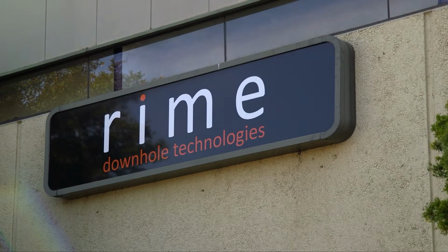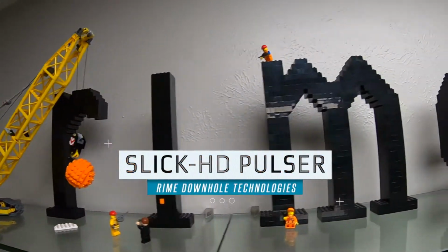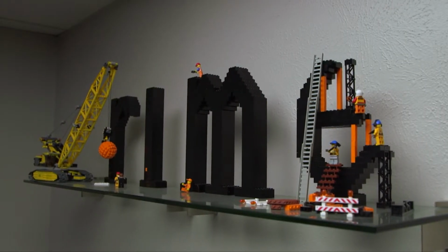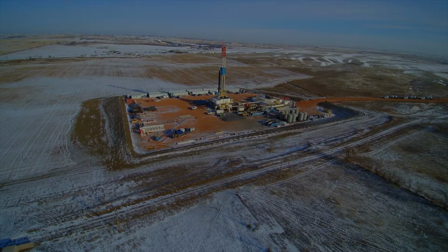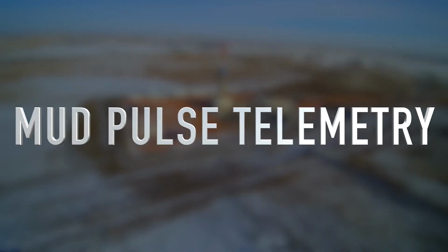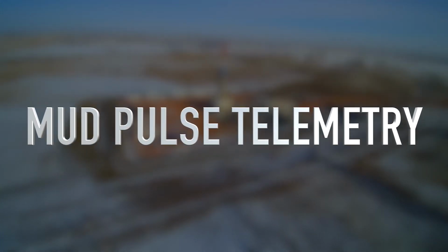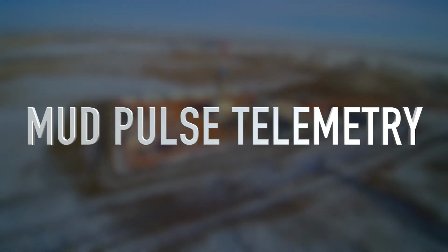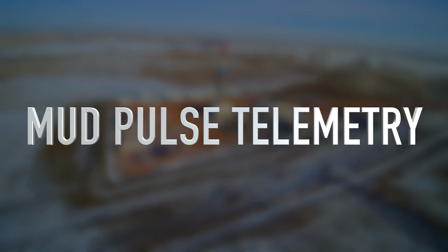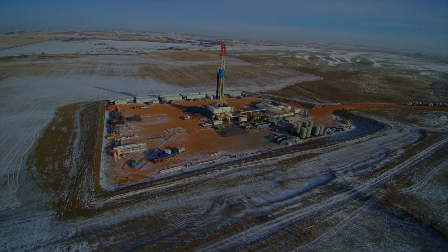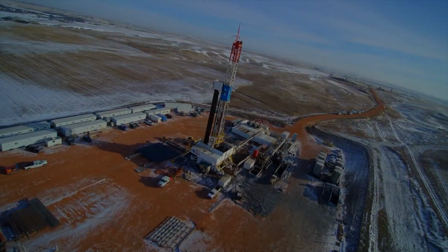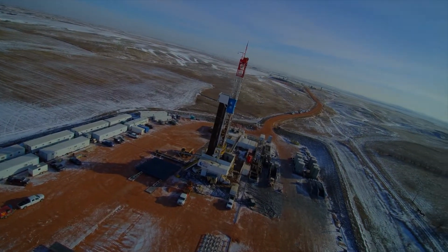We specialize in downhole drilling tools. We make measurements downhole at the bottom of an oil well during the drilling process, and telemeter this information to the surface in real time. One of the interesting technologies in this industry is mud pulse telemetry, where we open and close valves to make pressure pulses in the fluid flow and use those pressure pulses to encode data and send it to the surface. And of course, to do this, you need electronics, valves, sensors, and surface equipment. And Rime specializes in that particular industry.